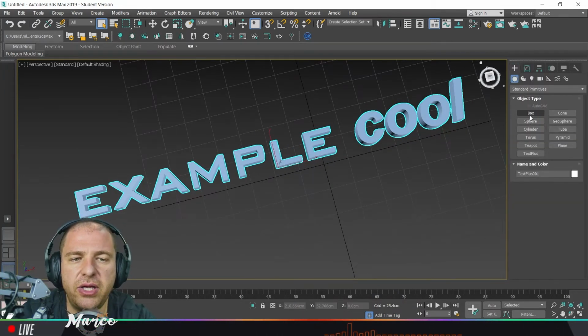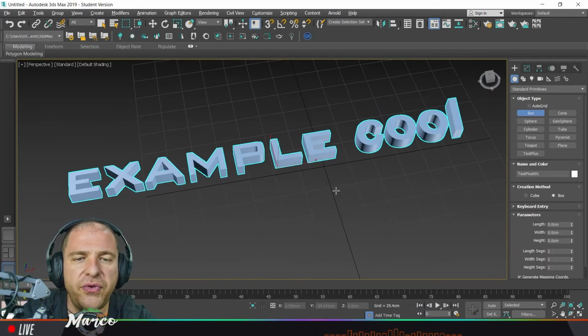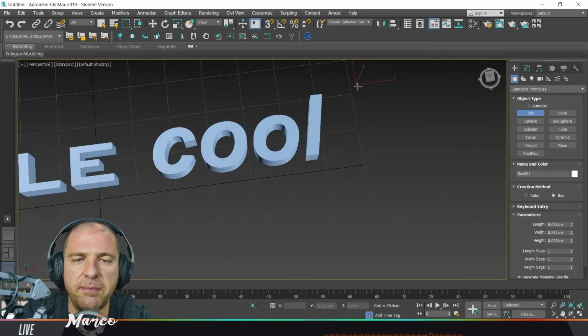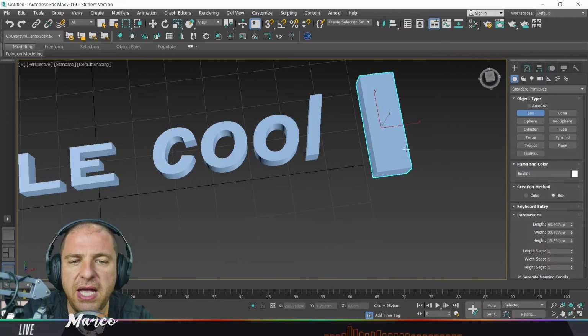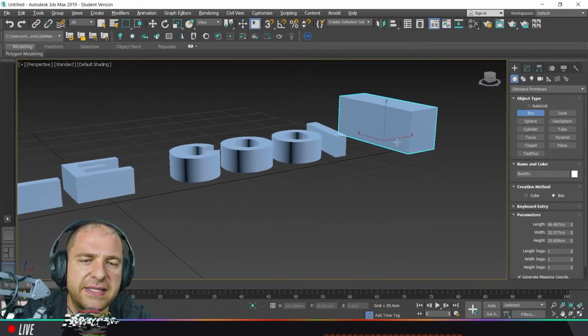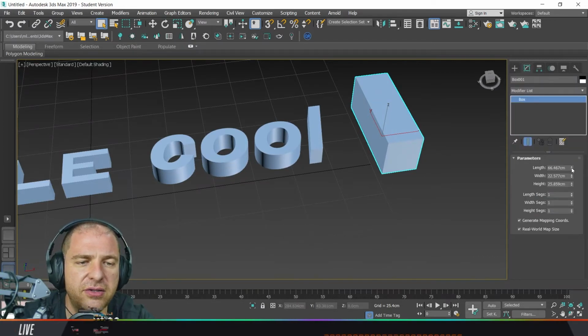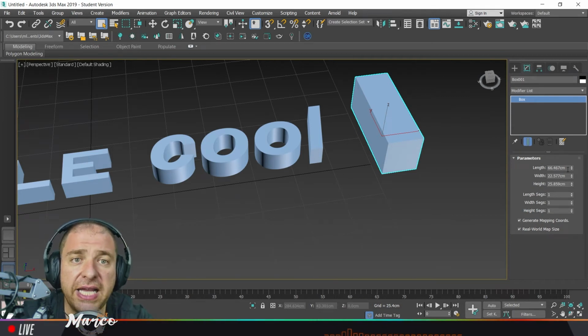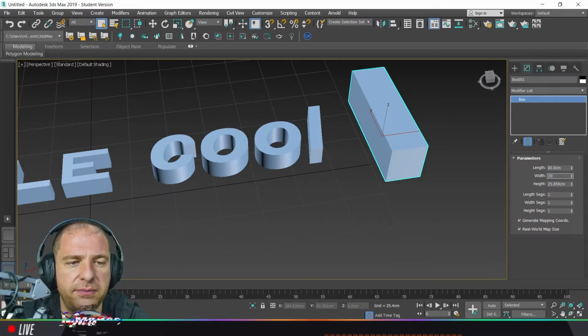What is interesting is that in this way all other objects can be modified. So if I want to make a box, I first have to go into the Create tab and make a box that looks more or less like something I like. Then, with my box selected, I go to the Modify tab and I start changing these parameters. I can change them in two slightly different ways: if I know the exact value that I want to obtain, I can simply type numbers in here,